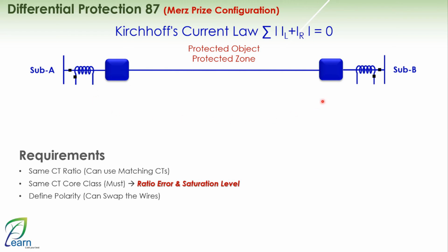Their currents in the secondary will inherently have a difference, and consequently, your protection system will consider that you have a fault. While the actual currents running in the equipment as primary are fine, with no issues at all, and no difference between them. Therefore, here you must use current transformers with the same ratio. Otherwise, you use matching CTs to ensure that the currents in the normal case are equal to each other on the secondary side of the current transformers.